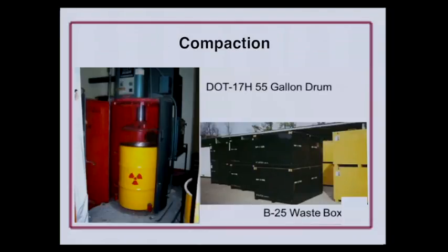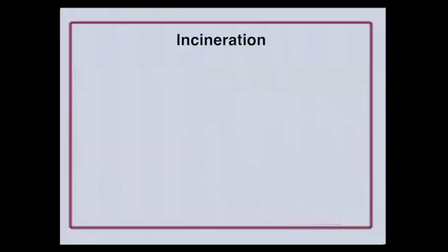Very effective. The plant I worked at in Arkansas, we had 2 of these, and that was one of the things the RPs did. We ran the compactor. Not just doing the radiological surveys, but actually putting the trash in it and compacting it. We later had a box compactor out at our rad waste building, and we did compact. And then, technology changes. They came up with a super compactor, and incineration came along. That was the next technology. Incineration is just what it sounds like. You burn it.